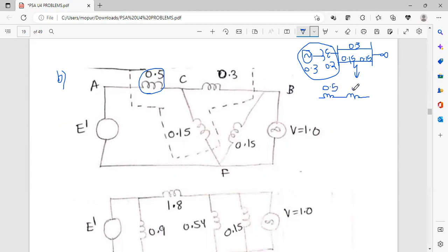Why? Because when the fault is in the middle, we should go for 3 cases. You can see the graph of the derivation of the equal area criteria for the second application. When the fault is in the middle of the transmission line, we will be having 3 cases: before fault, during fault, and after fault, and we will be getting 3 swing curves.